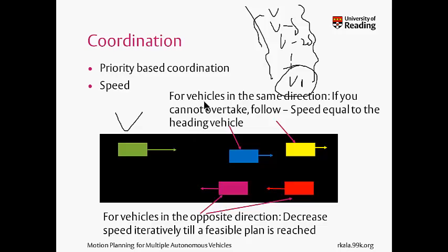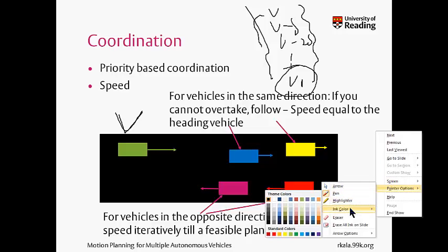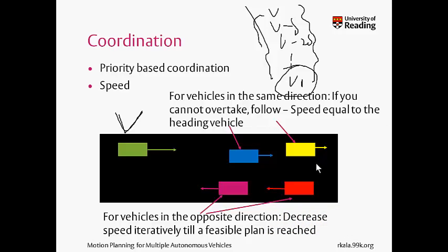If it says the path construction is infeasible, I do not let RRT get rid of it. I further ask it, why is it that you could not construct a path? What was the reason by which feasibility is not being catered to? And if RRT-Connect says I'm unable to construct a feasible trajectory because of collision with another vehicle, because there's another vehicle with which I'm again and again colliding and cannot surpass, then I'll ask in which direction was that vehicle moving. Suppose the RRT could not overcome this vehicle. It tried to expand a lot, it tried generating many samples all around here, but it still could not overcome this vehicle out here.